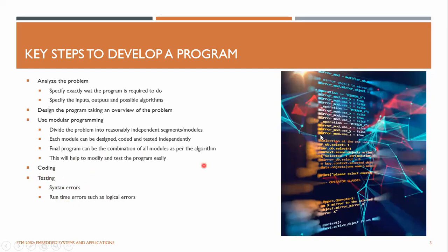And there could be some runtime errors. So your code is compiled and built successfully, and you just burn it to the microcontroller and it is running. But when you run it, you are getting some kind of errors. I mean, the data from the sensor is not what you expect. Say you have a reference temperature meter, a thermometer in your hand, and it shows 30 degrees, and you have a temperature sensor mounted and you are testing it.